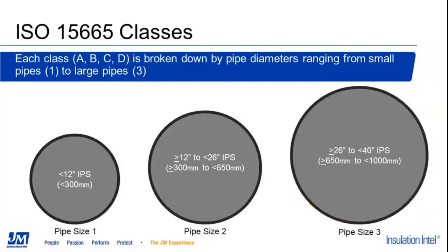Within those classifications, the performance levels are also broken down by pipe size ranges. The pipe size is directly correlated, obviously, to the amount of surface area on the pipe, and the amount of surface area can and will have a significant impact on the noise level, even with the same level of noise stimulus that is creating the noise.